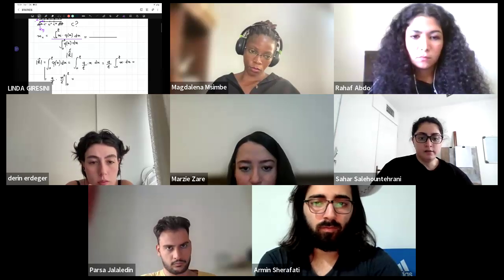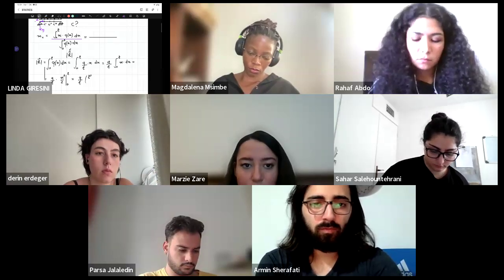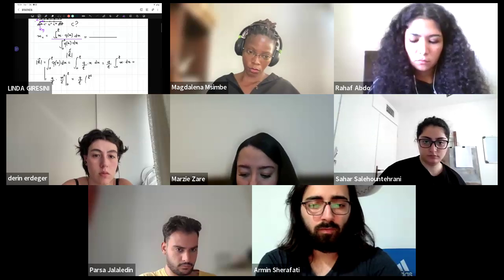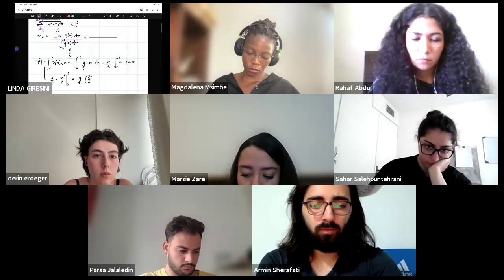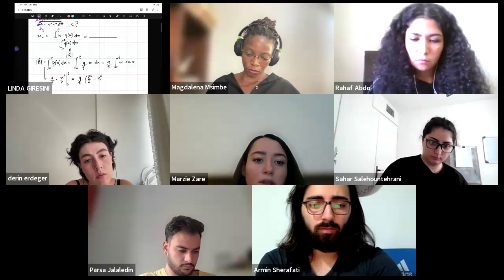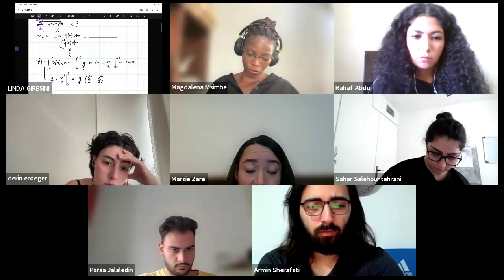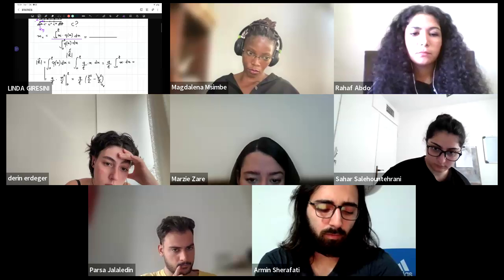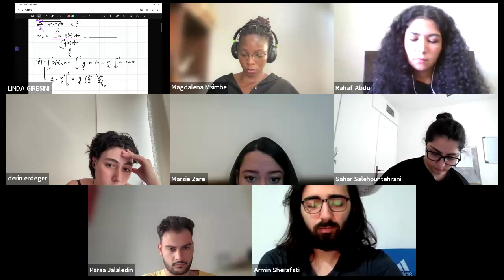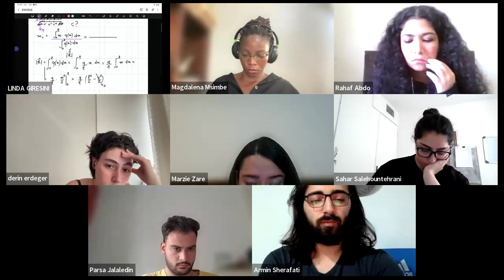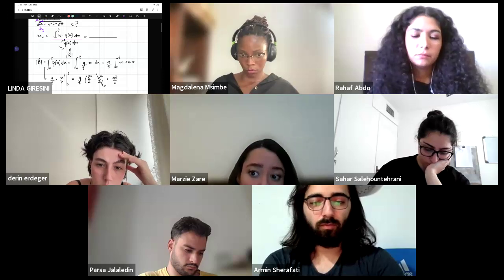Now you will have it clearer: q divided by L, and you first substitute L for x, so you have L squared divided by 2, minus 0 squared divided by 2. So this is a translation of this line. Of course, this number is equal to 0 because 0 squared is 0. And therefore, you have qL divided by 2, which is the resultant force.